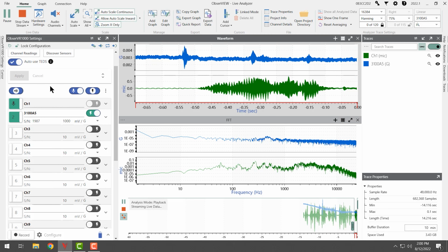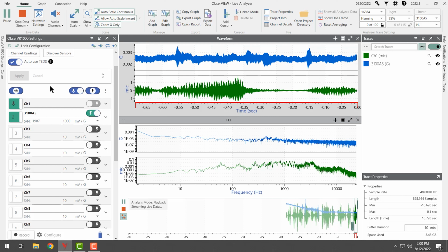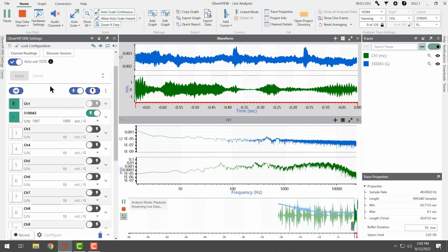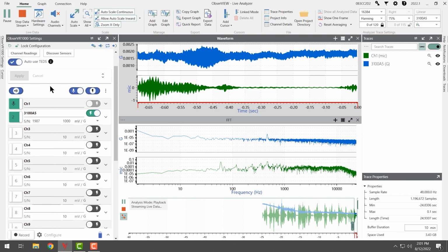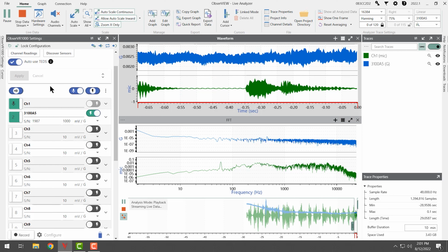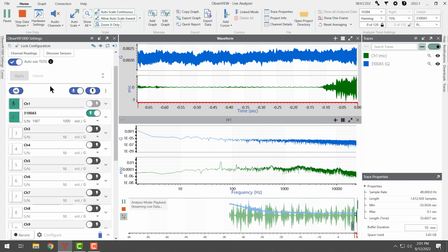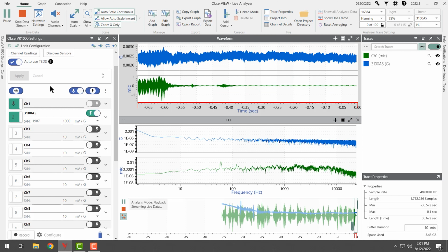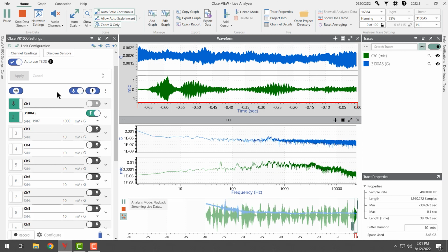We use it quite often as we go on the road to narrate what's going on in a particular test situation or as we're recording data, and that can get matched up to video and the accelerometer readings, and it's a really handy tool. But we wanted to show you today how to plug it in, how to set it up, and that very important fact that it uses channel 1. So you have to take your accelerometer away from channel 1 and plug it into another channel.